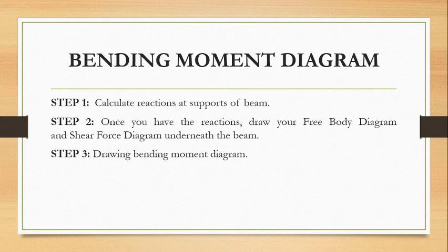So why do we need to find a bending moment diagram when we wish to see if the structure would be efficient or inefficient? Because we wish to see whether the basic load carrier unit, which is supposed to be a beam, is an efficient beam or inefficient beam. Because if within a beam there is insufficient resistance, that would imply that the beam will show some kind of movement.